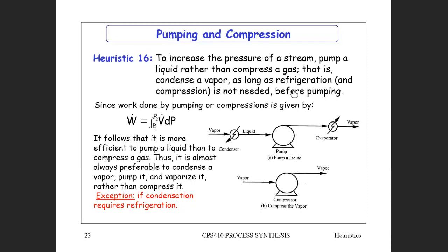Remember that 40 degrees is what we talked about when you've got cooling water at 30 degrees, 10 degrees C temperature difference for cooling it down. If your process stream is 40 degrees, then you've got your 10 degrees C difference to cool it down, and therefore 40 degrees is pretty much a boiling point cutoff, and that's again exactly the same.